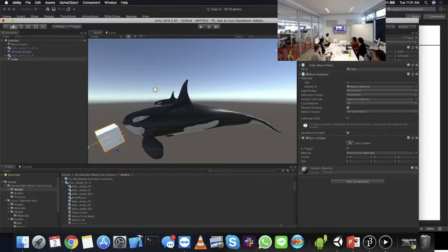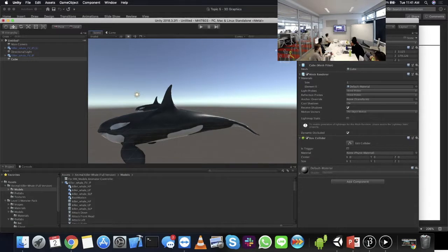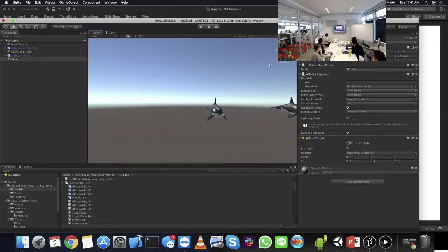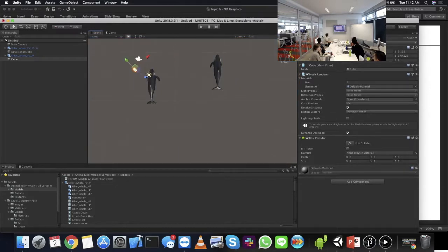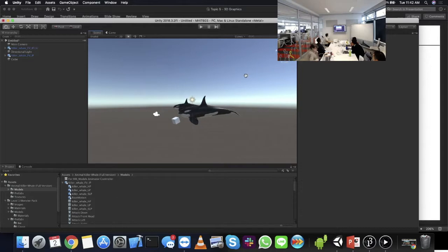Everything's in perspective by default. And you can see just under here, there are some controls that control the camera view. So I can move it around, and we can see that it moves. But if I want to align everything with the Z-axis, I can click on Z and the camera will move me to the Z-axis, or the X-axis, the Y-axis or whatever. So I can very quickly move the camera around 90 degrees at a time.